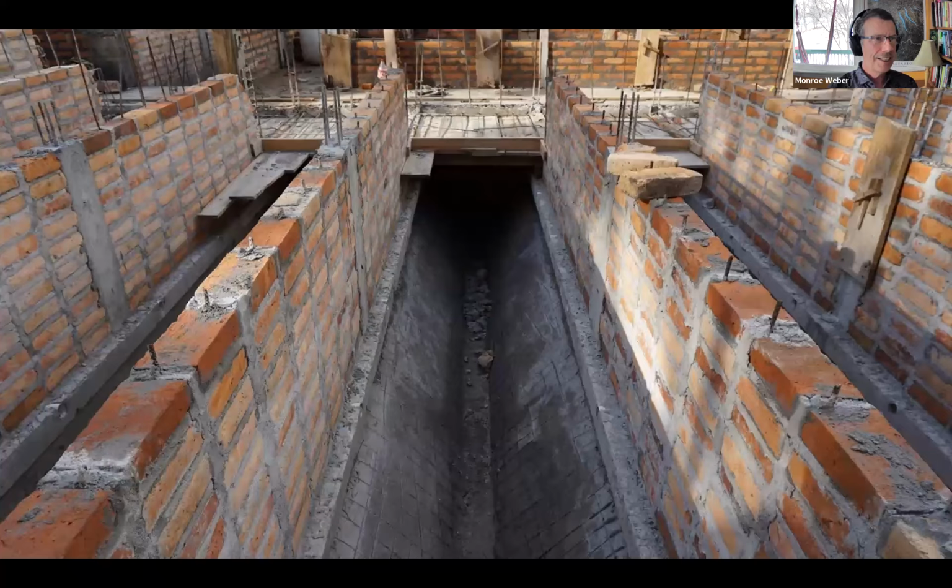For those of you who are interested in the structural engineering side, they use a very different way of laying bricks. If you think about bricks, you always want to lay them so that they're overlapped with each other, but you notice here they're not. And the reason is that these are load-bearing walls that have to be waterproof and have to resist significant hydrostatic pressure, because you have to be able to drain one tank while the others are still online. And that means there's the full water pressure pushing on these walls in either direction, depending on which side you drain. And so to accommodate that, there's rebar.